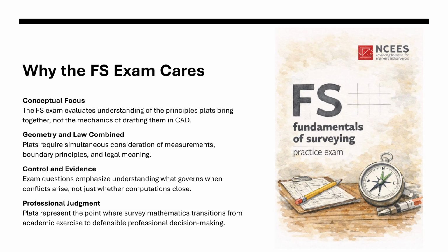That is why the exam does not stop at asking whether a traverse closes. It asks what controls when it doesn't. It asks to know whether you understand why a monument might outweigh a distance, or why a recorded plat can carry authority beyond a set of computations. In practice, a plat is where survey math stops being an academic exercise and starts becoming professional judgment. The FS exam reflects that reality by treating plat-related knowledge as conceptual, not procedural.